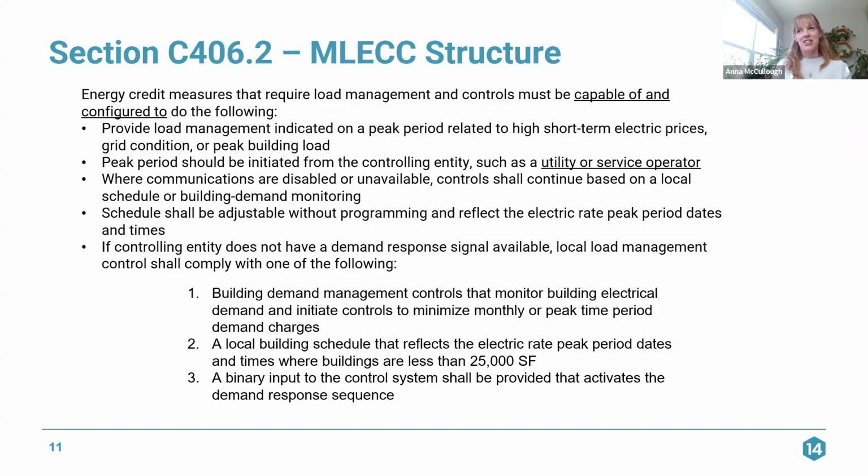So this section is talking about demand response. If you are achieving a credit under section C406 for renewable or for load management, within the mandatory sections of the code, we have to install thermostats that can respond to a call from the local utility to increase or decrease the temperature to reduce peak demand.